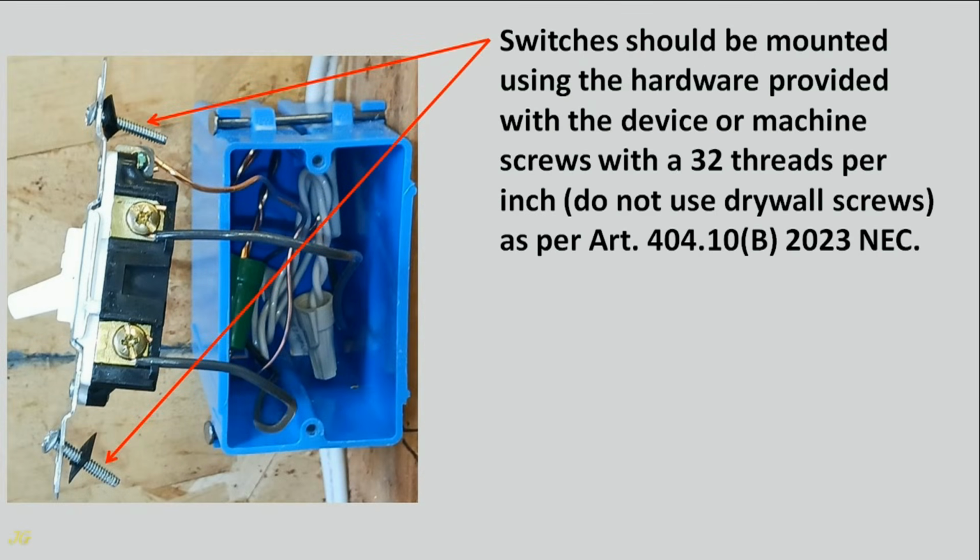Switches should be mounted using the hardware provided with the device or machine screws with 32 threads per inch. Do not use drywall screws, as per Article 404.10, b. 2023 NEC.